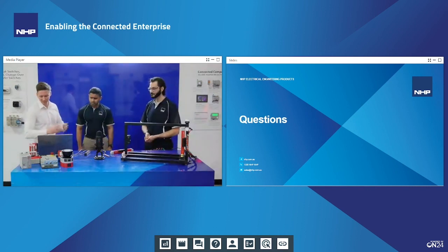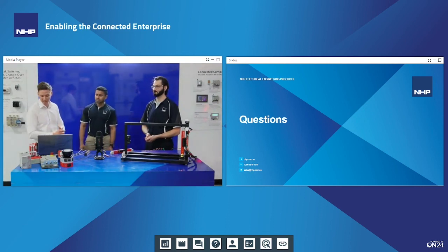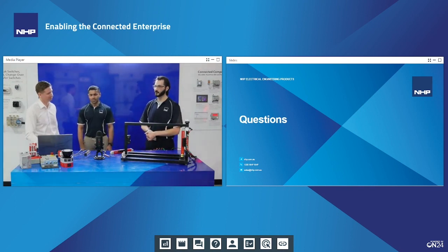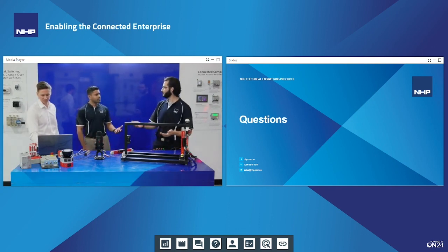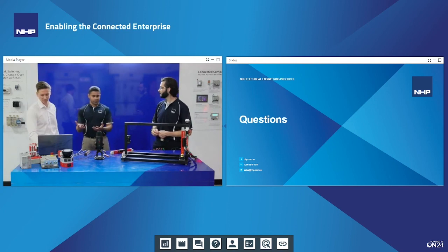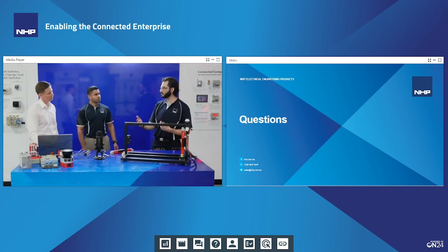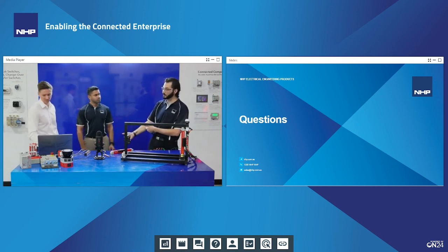Matthew's asked, is CIP Safety vendor-specific? Obviously, we're talking Allen Bradley here today, or is it widely available as an open protocol? Open. Many other devices in the market can opt to use CIP Safety, not necessarily just Allen Bradley Rockwell. The point though is that you might not necessarily have an add-on profile for that device, so there might be a lot more integrating that you need to do in your safety PLC or in your SCADA to handle this third-party vendor. But no, CIP Safety you can incorporate in any device with a network card, really.